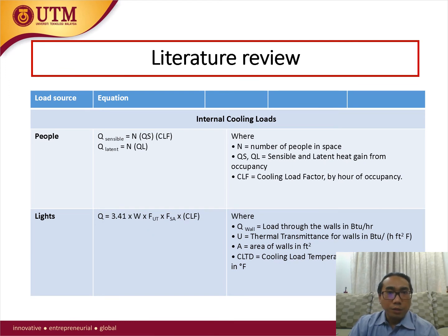The various internal loads consist of sensible and latent heat transfer due to occupants, product, process, appliances, and lighting. The lighting load is only sensible. The conversion of sensible heat gain from lighting, people, appliances, etc. to space cooling load is affected by applying the appropriate cooling load factor (CLF) to account for the time lag of the cooling load caused by the building mass.